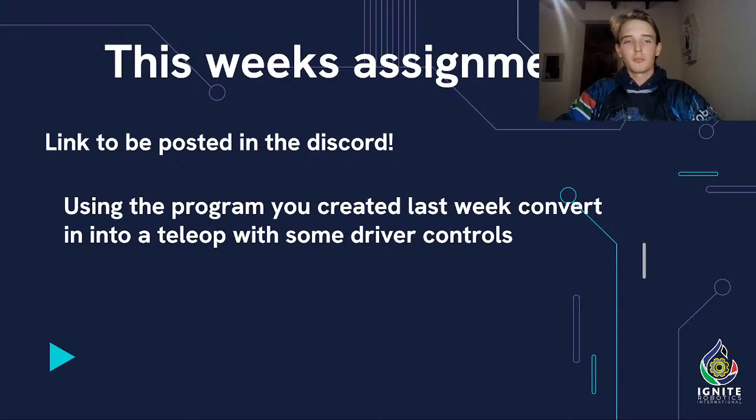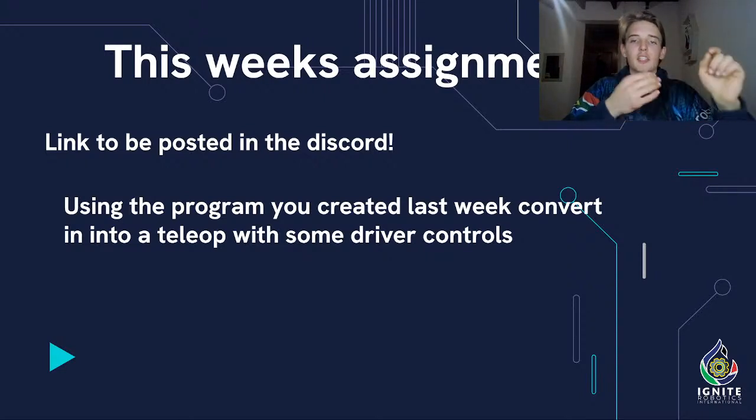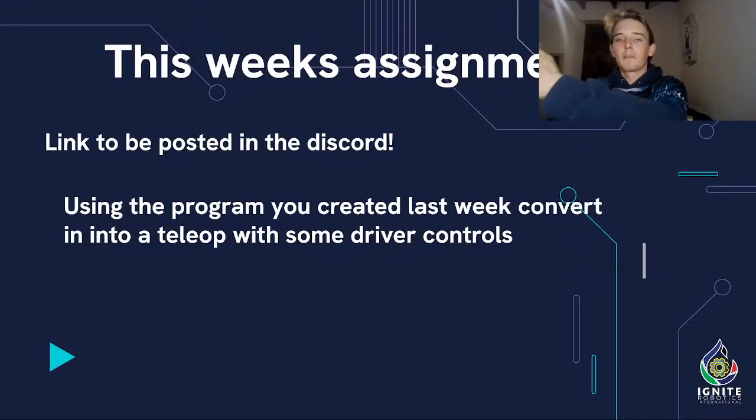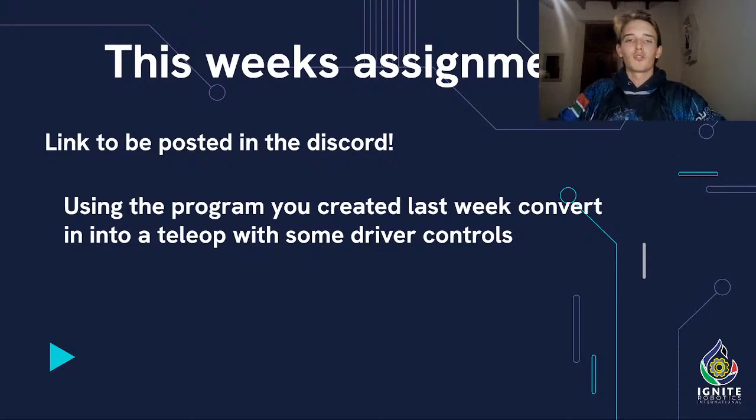Yeah, so I'm saying using the program you created last week, convert it into a teleop with some driver controls. So think about, okay, now I've got an omni-wheel drivetrain, this is what I need to do. I need to add more motors, I need to initialize it, I need to put the names in for the configuration that I would have, so like left drive or right drive, and then this is what I need to do to get the driver input, and this is how I turn it into commands for the hardware to follow, right? So yeah, I hope that makes sense.